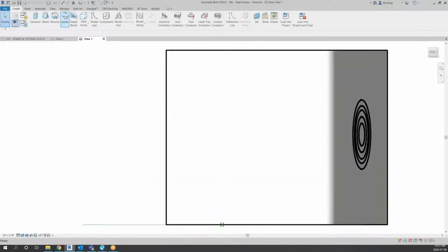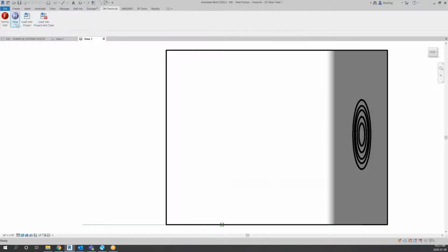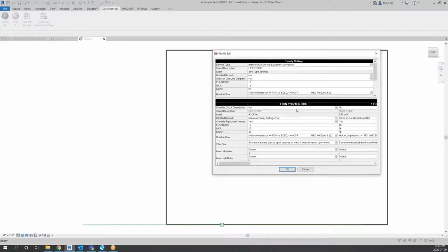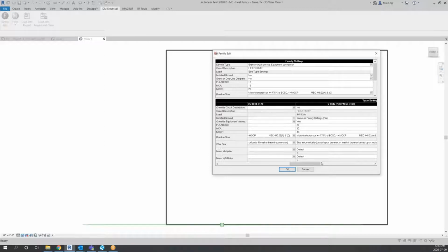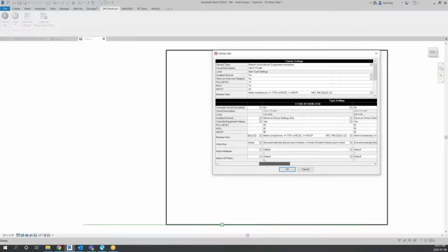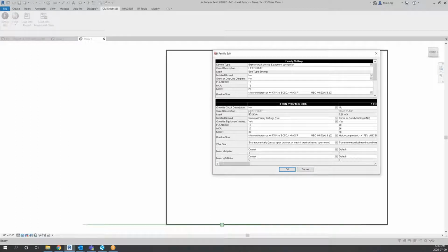We are instead setting all those current ratings here under Design Master properties, so that when we set up Design Master, it automatically derives into the family type and then into everything else that connects to it. So the 3 ton has an FLA of 45, the 5 ton has an FLA of 25, etc. Away you go. All of them use the description heat pump.